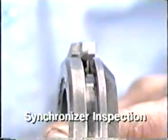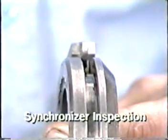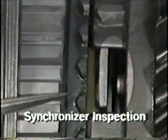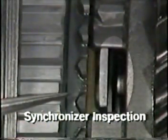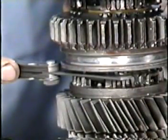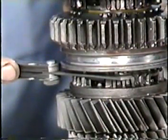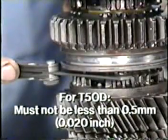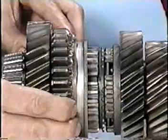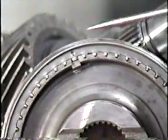Begin inspection of synchronizer assemblies by visually inspecting for signs of wear at the shift fork contact surfaces. Inspect the synchronizer ring for rounded clutch teeth or a widened index slot. Check for blocking ring wear by measuring the distance between the face of the ring and the face of the gear and comparing to specifications in the shop manual. If the gap is too narrow, it's a sign of unacceptable wear. Finally, check the synchronizer sleeve for free movement on the hub. Always take note of alignment marks.